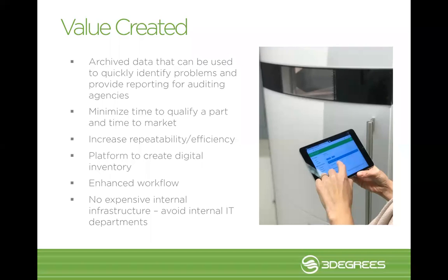Additionally, it hopefully increases workflow and repeatability, because we're tracking a number of inputs such as particle size distribution or lot number of the material. So if you have an issue and you can trace it back to specific factors, maybe you had a bad lot from one of your vendors and the last batch of 10, 15 parts wasn't coming out correctly, you'd be able to quickly identify that and trace that back to a specific build date or specific lot number, and quickly identify what was the issue, and perhaps save some inventory and not scrap everything.